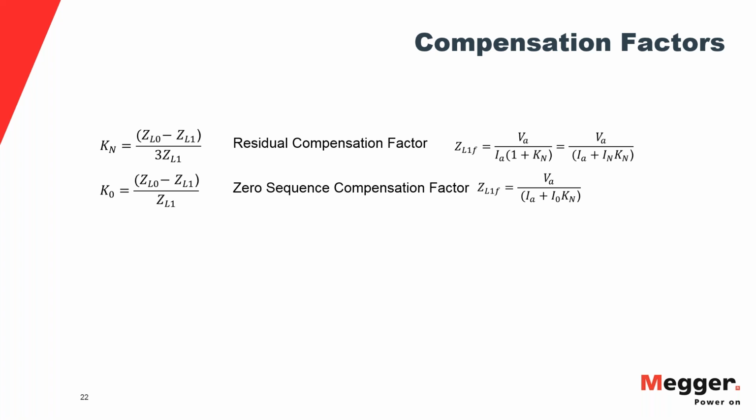Now, if you're talking about testing, then you have to either use the compensation factors yourself. There are tools out there that you can use for that, and you can calculate the compensated impedance and then apply a fault to that impedance. Or you can use a tool like the one I presented in the software that does that magic for you.